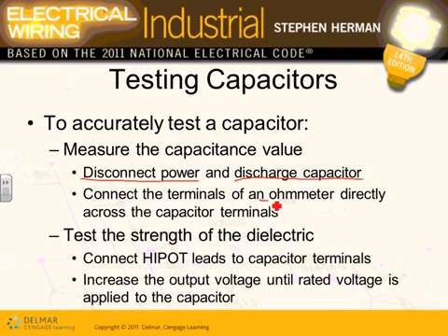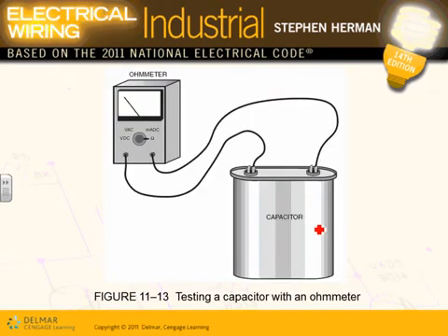Connect the terminals to an ohm meter. Then there's an ohm meter, guys, and a high potential test for the insulation. All these are different tests. They test the dielectric material. What is a capacitor? Do you guys know what a capacitor is, right? Remember the old days? It's a metallic, say a copper plate here and a copper plate here, and in between them a dielectric material that does not conduct electricity. That's what a capacitor is. So if that dielectric material becomes too conductive, then it shorts or it opens, or there are a lot of issues with testing the capacitors.